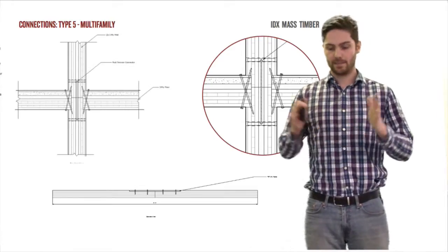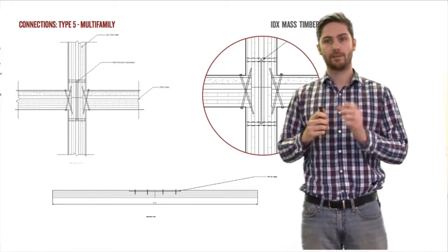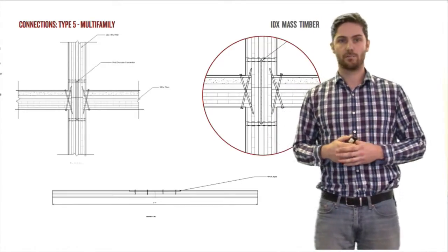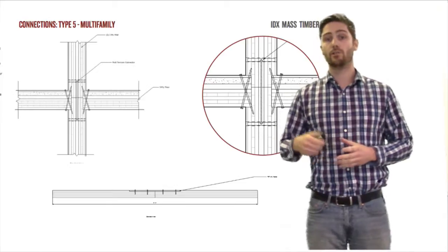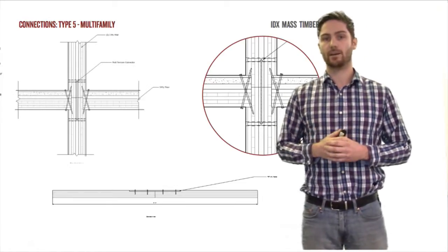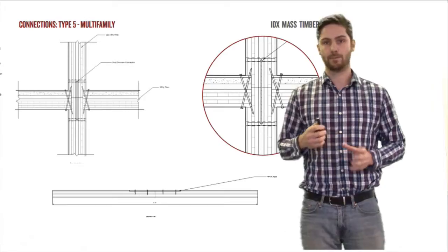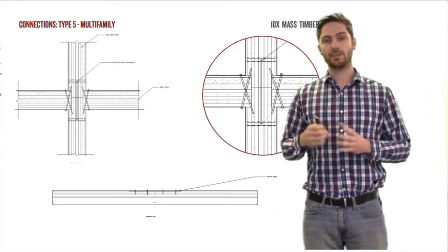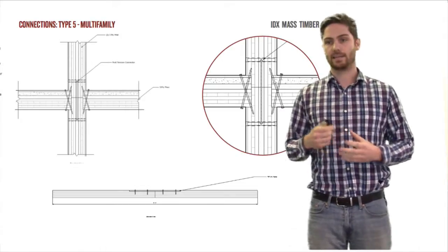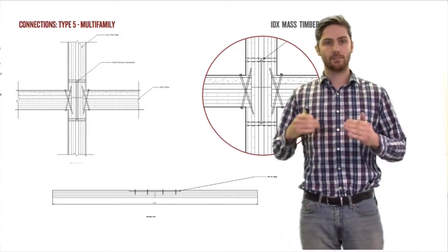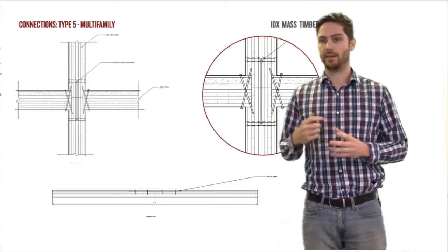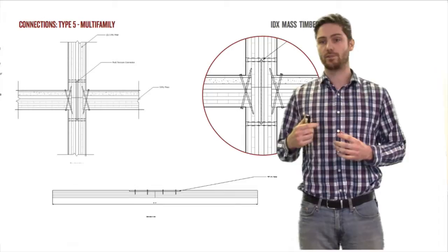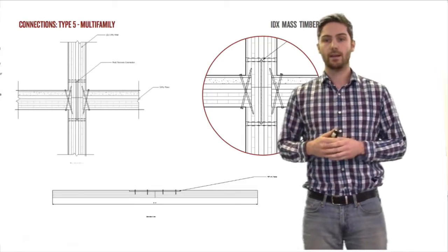Those two 3-ply CLT panels come and they sandwich together to leave just enough gap, and this gap is in order to be able to run conduit, electrical, mechanical, things of this nature through our building. And so because of the bearing wall system, we needed that gap to be able to run things of this nature through our building. And so these two 3-ply panels are connected through bolts, and then the diaphragms come, they hang off of this wall, and as you can see, to secure and fasten that into the wall, we have two toenail screws going through either direction.